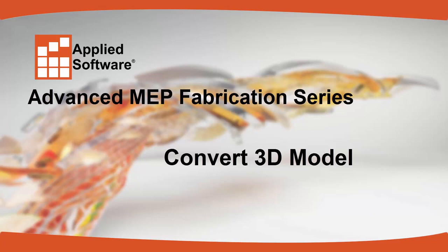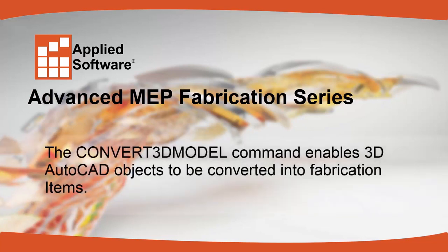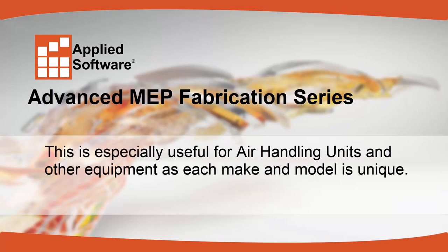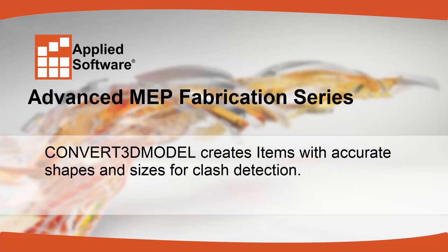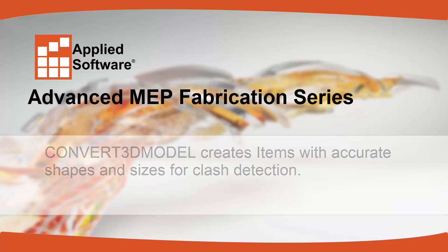Convert 3D Model. The Convert 3D Model command enables 3D AutoCAD objects to be converted into fabrication items. This is especially useful for air handling units and other equipment, as each make and model is unique. Convert 3D Model creates items with accurate shapes and sizes for clash detection.